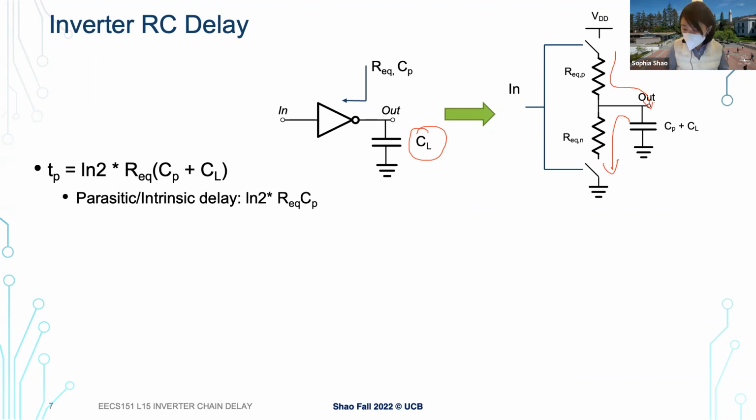In addition to the load capacitance, we also mentioned the parasitic capacitance, and now you'll see where this fits in. That's basically the drain capacitance that we talk about in the MOS design. So this is a parasitic capacitor we also need to charge. Those are the two capacitors that we need to charge, in the designs we are driving here.